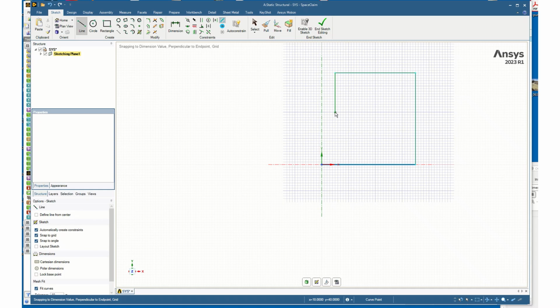And now coming back, I know that the beam member is 10 millimeters wide, so I can move in here 10 and then just left click, move up here 20, left click, move over here 40, left click, down here to 50, left click, out to the end, left click, and then back to close it and left click. And there's my geometry cross section.